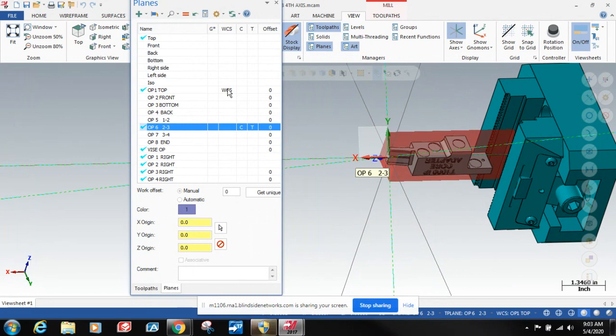I set the WCS to one thing and then make everything else relative to it. I want to set one work offset at the center of my rotary. I want to touch off the face of my dock to find the center of the rotary, set that as my work offset, and have everything else relative to that. So that's what my WCS is. They call that the world coordinate system, but generally it's going to be your work offset when you're doing rotary.